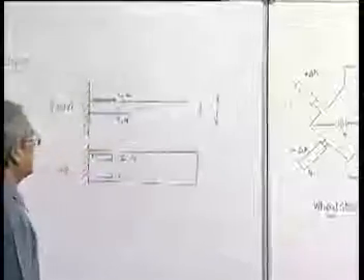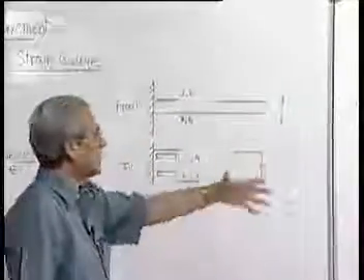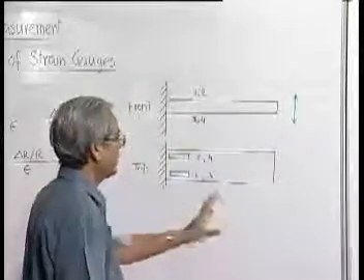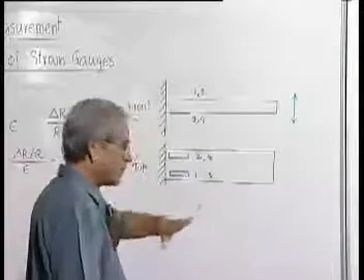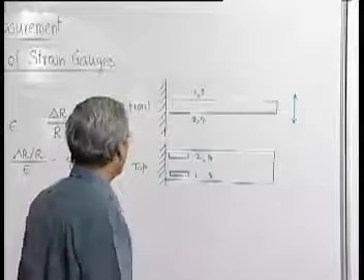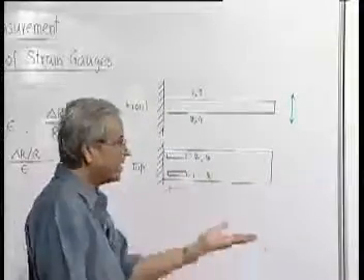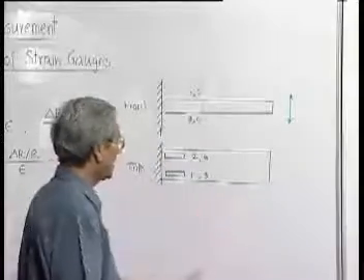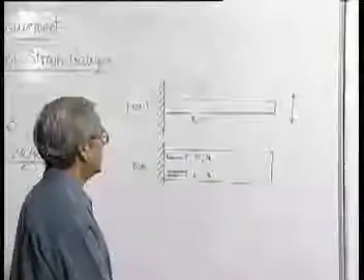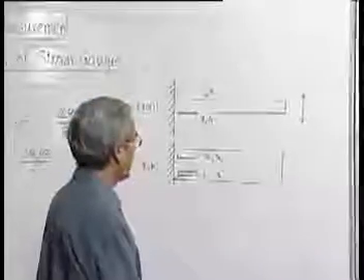In many cases, when a machine is vibrating where we cannot put any pickup, we can scrape the surface and attach a proper strain gauge, and sense the strain the surface is subjected to, which gives us an idea about the vibration it is undergoing.